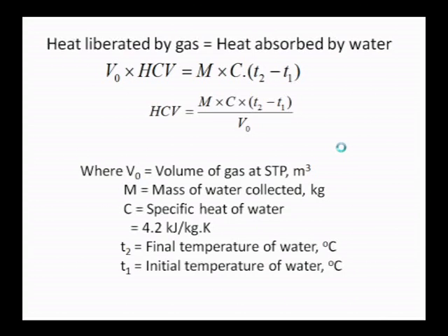If the product of the combustion is cooled to room temperature and the steam formed is condensed, and if you note down the heat absorbed by that steam and subtract it from the HCV, you are going to get the lower calorific value of the fuel.